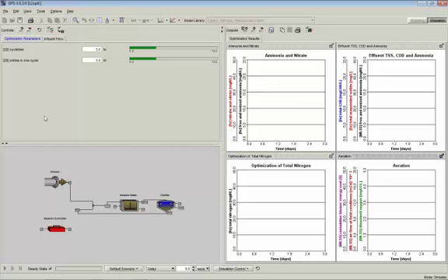So what I'm going to do is I've put the 2 parameters up here that are part of that aeration controller. So one being the total length of the cycle time, and the other one being how much of that time is the aeration on. So right now, I'm saying for every 3 hours, I want the air on for the whole 3 hours.